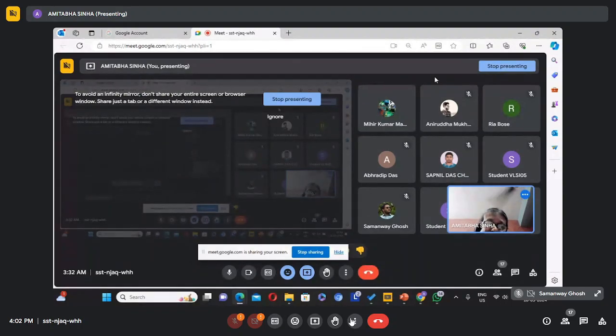But let's say your bandwidth is such that you have to sample at T by 4 rate. Then what you will do? You use 4 A to D converters. You give the same start signal to the first one, then after T by 4 time to the second A to D converter, then the third one, then the fourth one.